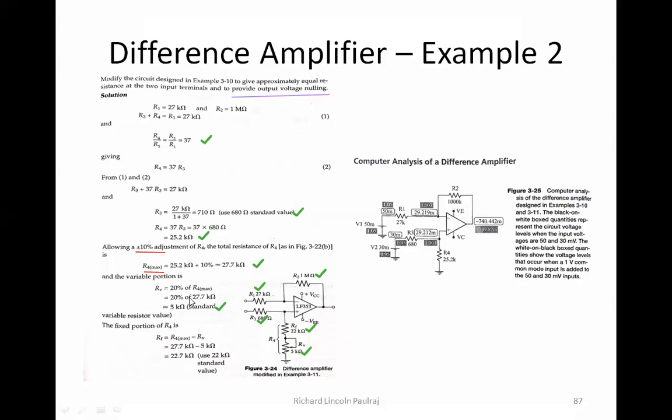One small thing that you need to remember here is always take the R4's maximum value. How you will get the maximum value? Based on the tolerance, okay, plus or minus 10% is always taken as standard, okay, and RV is going to be 20%. So remember, 10% for tolerance, 20% for variable resistance, okay, both are taking R4 into consideration, right?